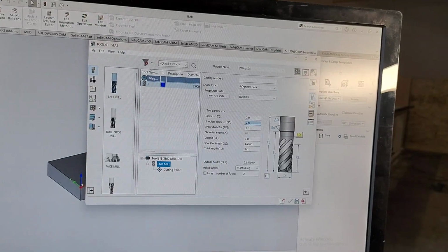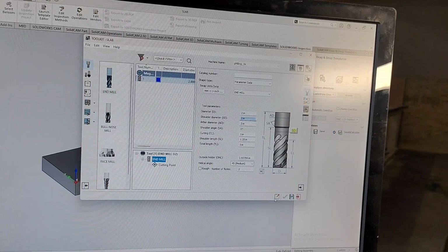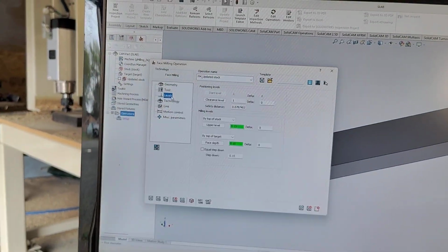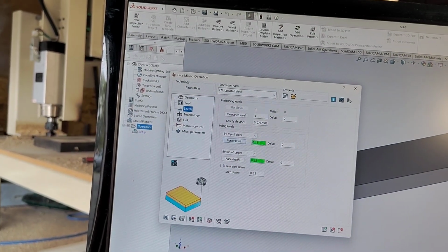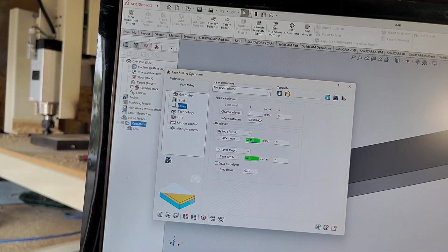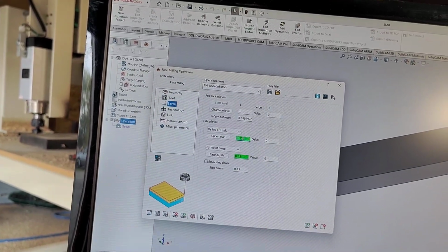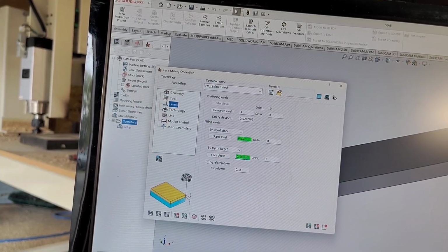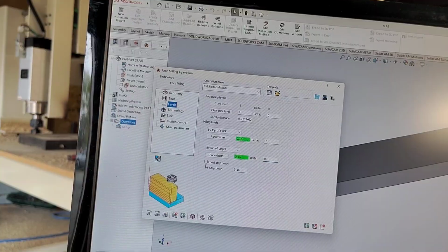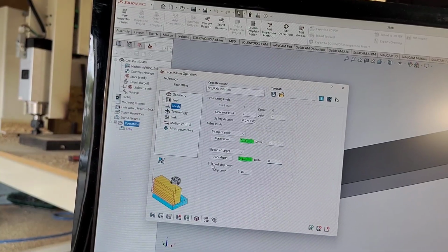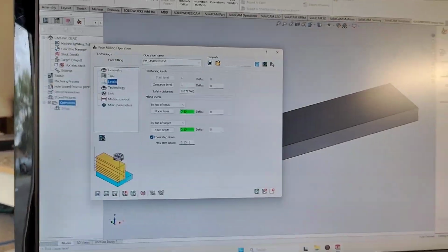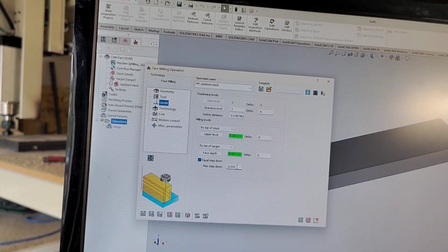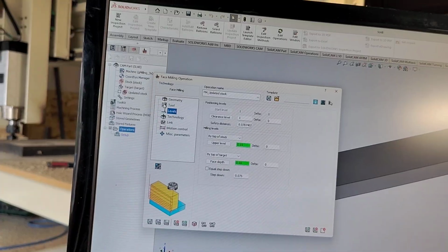And it will auto-populate reasonable values in all this. And check the box. Levels. So the upper level is 0.15 based on the extra stock we have. And the depth is 0.15, leaving a delta of 0. If you want to do equal step downs, you can do it here. You could say 0.075, and that would do 2 passes, 75 thousandths deep. But we don't want that.